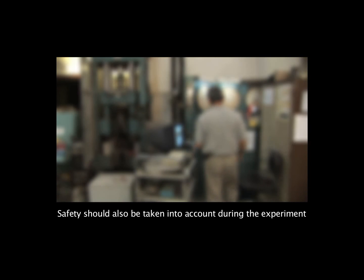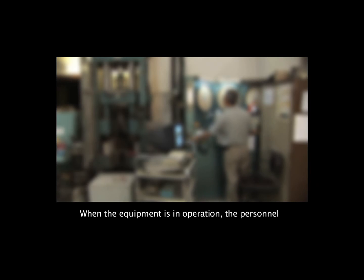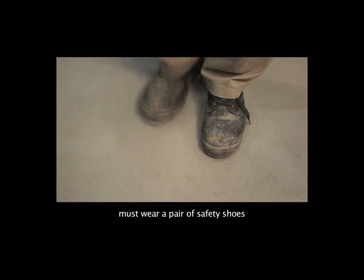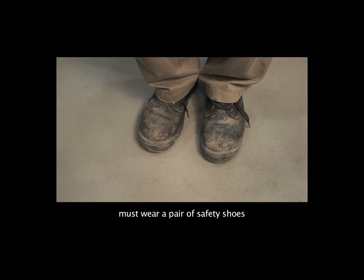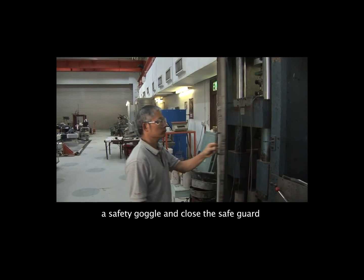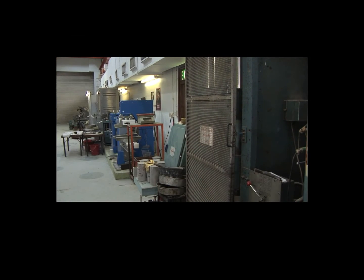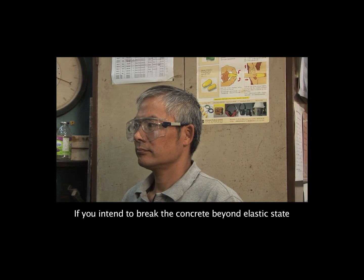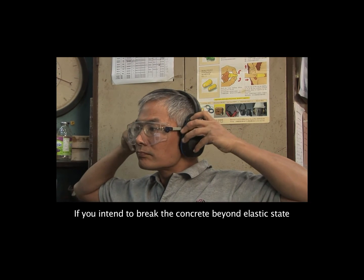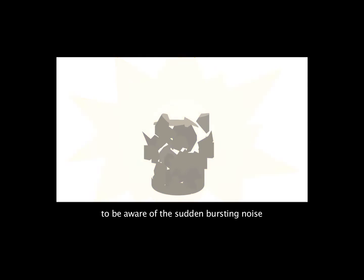Safety should also be taken into account during the experiment. When the equipment is in operation, the personnel must wear a pair of safety shoes, safety goggles, and close the safeguard in front of the compression machine. If you intend to break the concrete beyond elastic state, always wear an earmuff and alert your neighbours to be aware of the sudden bursting noise.